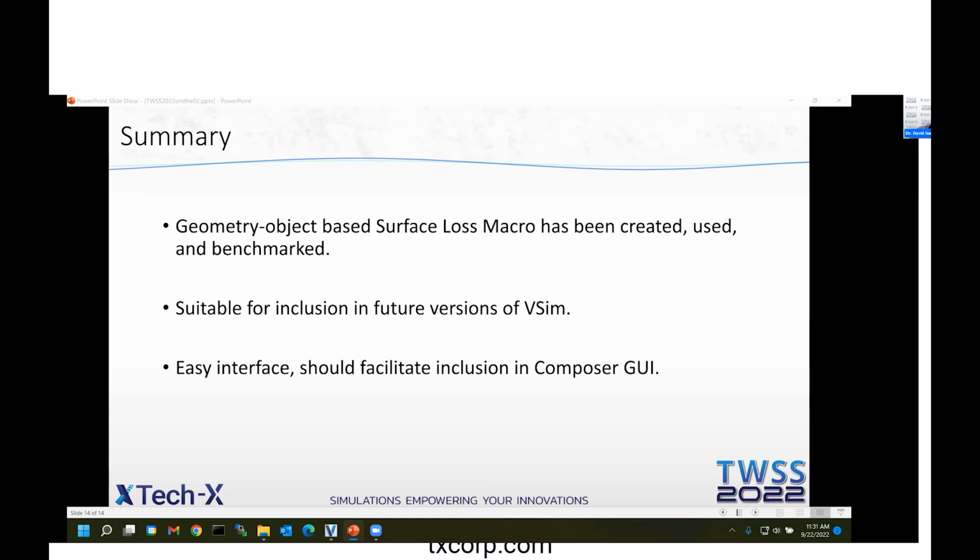When you're using a PEC, E surface is of course 0, and so there is no flux across that. As we do this, we are not actually computing an E surface per se. We are folding it into Ampere's law and using that lossy parameter instead.